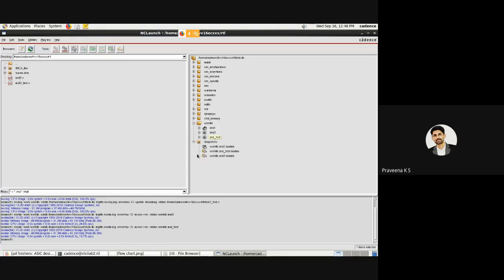under snapshots, for testing your code, select the and3_test module. So don't select the and3 module. This is a Verilog code, so we are about to test the simulation. You have to test only the and3_test module, the test bench module only. Fine, you select that, then you have to go for simulation. You have to launch the simulator.